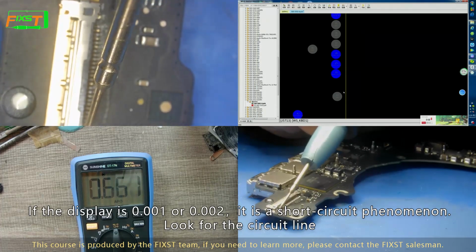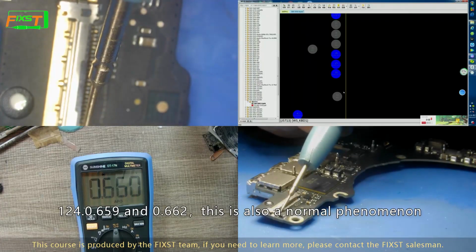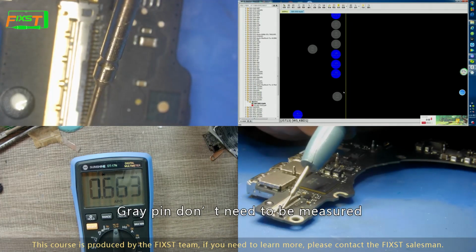Look for the circuit light. Then let's look at the second pin. 0.659 and 0.662, this is also a normal phenomenon. In actual maintenance, we only need to measure the diode value of the blue pin. The gray pin doesn't need to be measured.